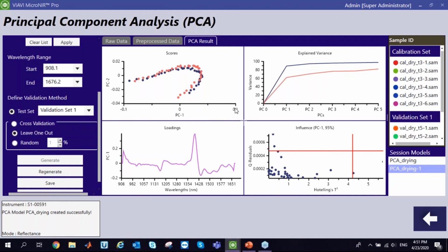And you can see that we have a complete overlap of the first batch, the golden one, the one that I want to consider as reference, and the one that we just acquired together. So it means that principal component analysis can be used for understanding the process, for following the process, and also to detect problems of the process. So if you see the PCA projection going out of the golden one, it means that something is going wrong inside your system, inside your process.